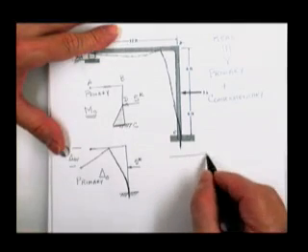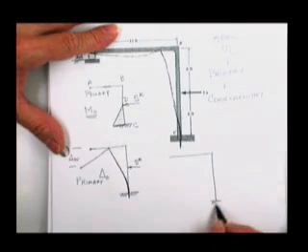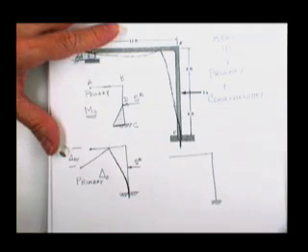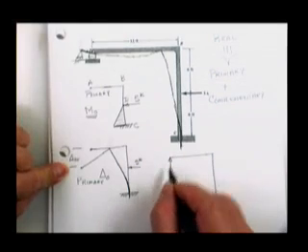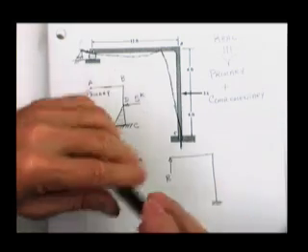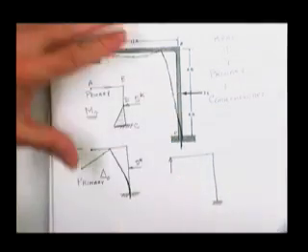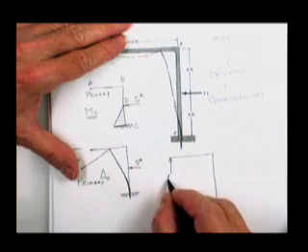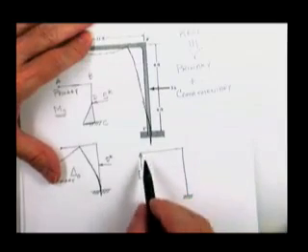Then we have, sometimes they call it a secondary structure, sometimes they call it a complementary structure. And the loading on it is that loading required to get rid of this serious problem right here? That would be a reaction at A vertical. Tell you what, let me just admit the truth. We're not going to put the whole R sub A on there. We're going to put a 1. And we're going to see what the moment diagram looks like.